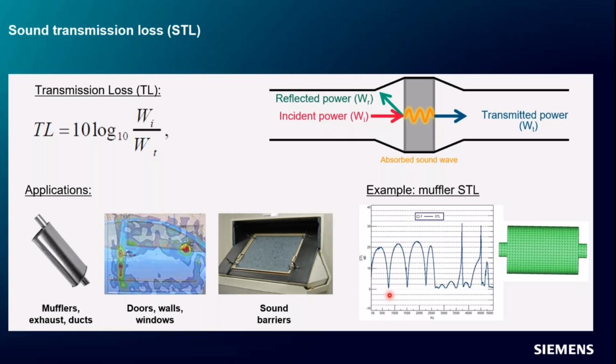So if I look at this, it's about 750 hertz, double that is 1500, triple that is 2250, right? So there's some harmonic thing going on here, and that has to do with the geometry of this particular expansion can. So that 750 hertz drop in transmission loss is because that's the natural frequency of the air cavity in that expansion can based on the dimensions, okay? So the air is really good at moving back and forth at those three frequencies, and as a result, the sound goes right through, or even is helped and gets magnified by the expansion can. So you'll always see these areas where it's really good, and then places where it's not quite as good, and that's based on the geometry.